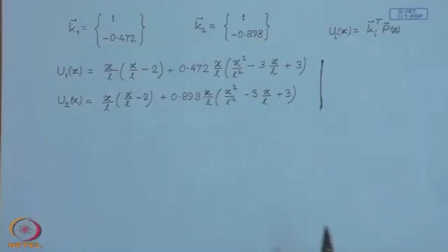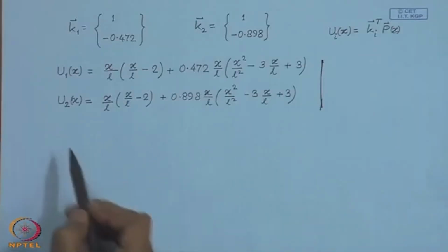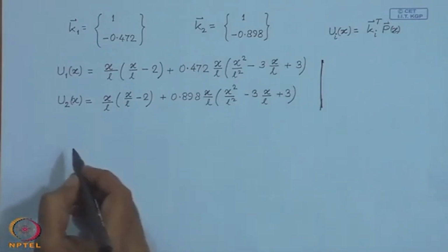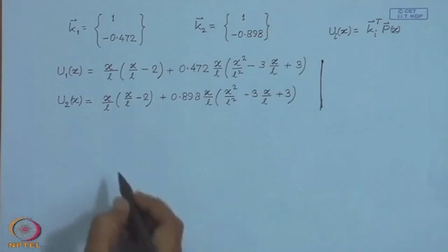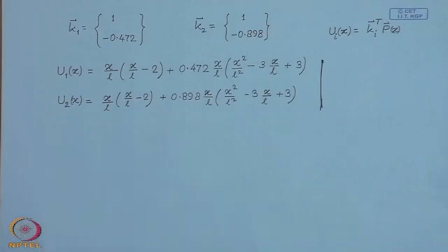Now, this Galerkin method is a method for discretizing the equation of motion of a continuous system. So, we can use this also when we have external forcing, which we will discuss later on in this course.